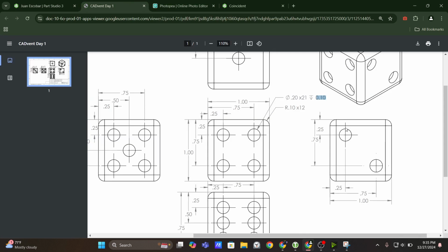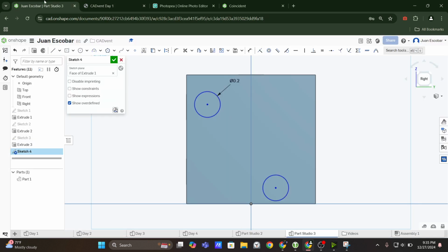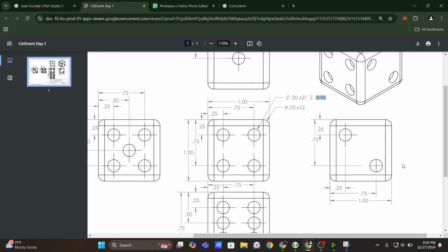And now we're going to add our dimensions from here to the edge. Let's look down because we do have a dimension down here, from here to the edge, looking at the arrows. See, these are pointing to that line. Check where the arrows point. So basically from here to here, it's going to be a distance of 0.25. So I'm going to add a dimension of 0.25 from here to the edge.